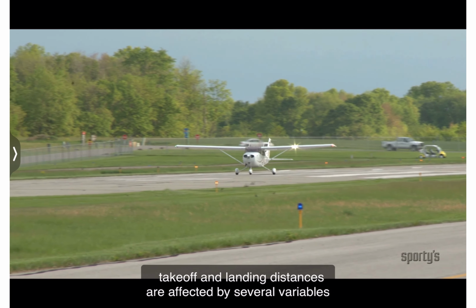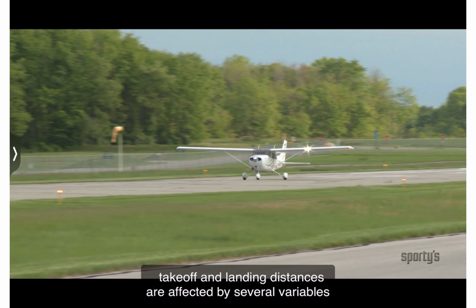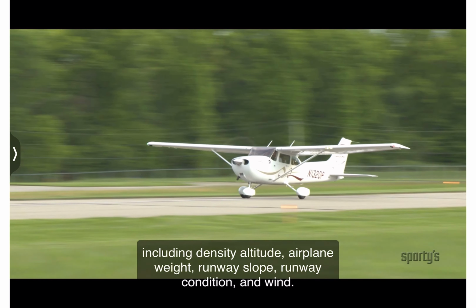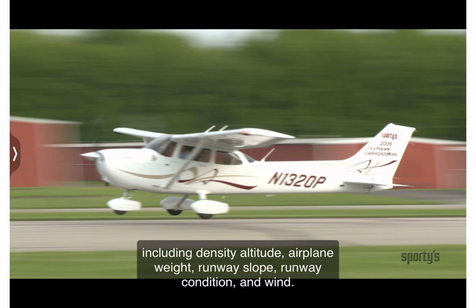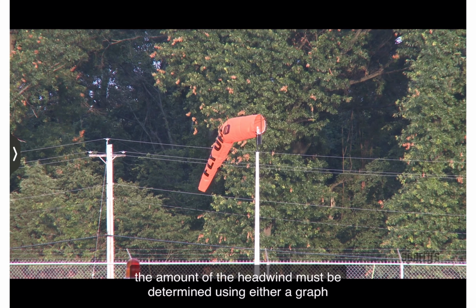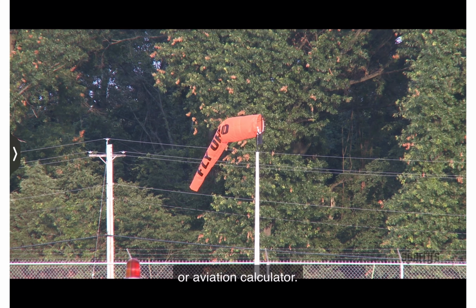Takeoff and landing distances are affected by several variables, including density altitude, airplane weight, runway slope, runway condition, and wind. If the wind direction is at an angle to the runway, the amount of the headwind must be determined using either a graph or aviation calculator.